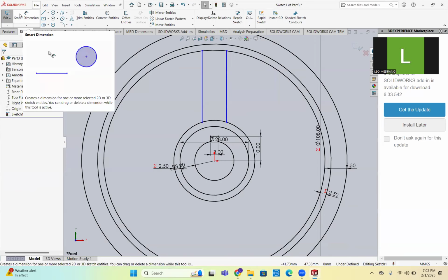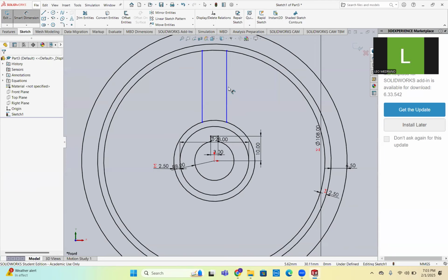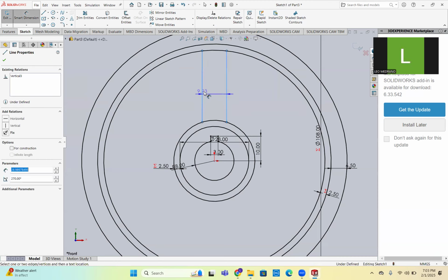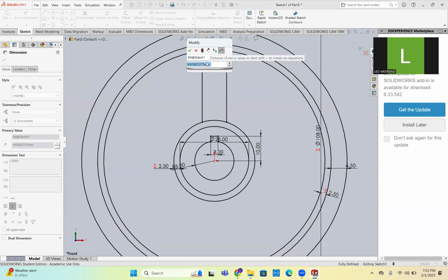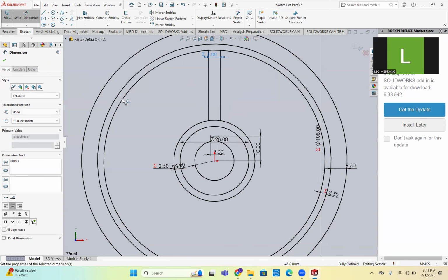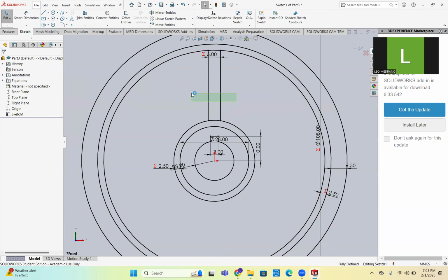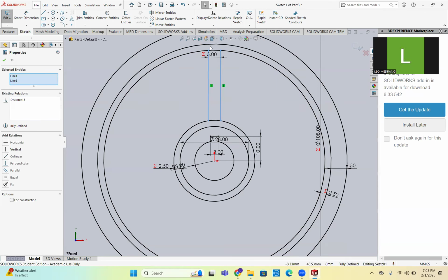So what you can do is you can do the math, which isn't bad, 2.5 times 2, or what you can do, SolidWorks has the ability to do simple equations when you're doing the dimensions, which is equals C times 2. And you can hit check. Awesome, 5.